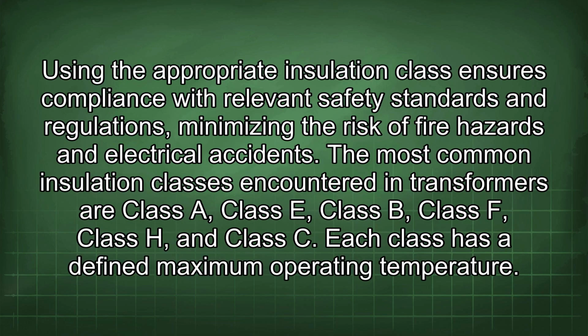Thirdly, it complies with safety standards. Using the appropriate insulation class ensures compliance with the relevant safety standards and regulations, minimizing the risk of fire hazards and electrical accidents. The most common insulation classes encountered in transformers are Class A, Class E, Class B, Class F, Class H, and Class C. Each class has a defined maximum operating temperature.